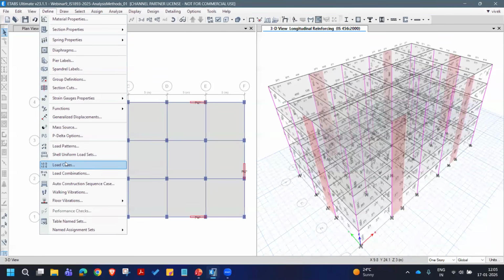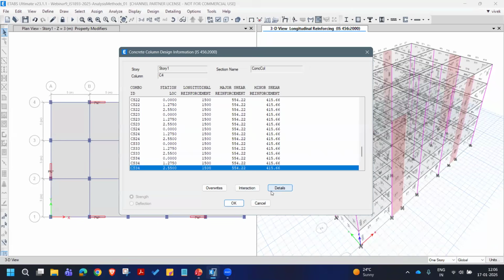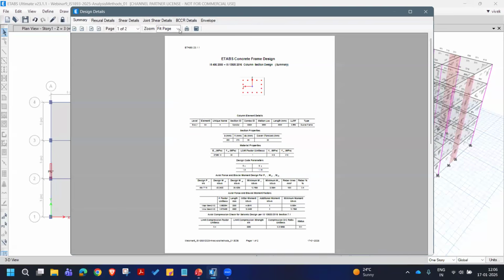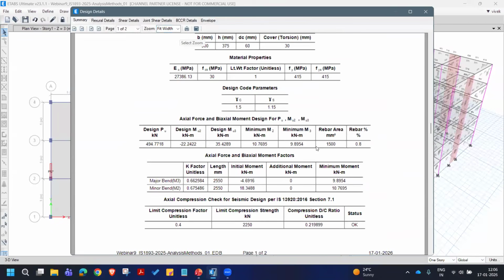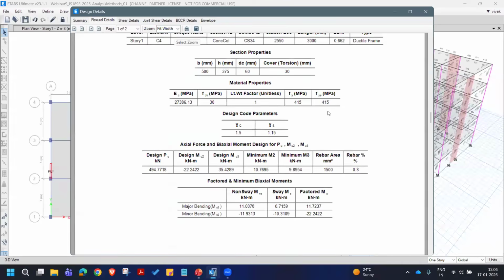converting the design load combinations to nonlinear static that will have the P delta effects, right? So this is only to cover that clause of the code, but what you will get is after the design, when you right click and quickly get into the details, and in the summary, you can see the K factors used, less than 1, it means these a non-sway category of the frame.